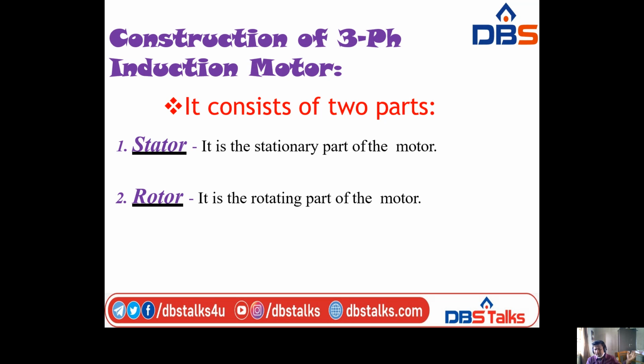As I said in the first slide, as we apply three-phase AC supply to the stator winding, it develops a rotating magnetic field, RMF, rotating at synchronous speed, right? That leads to generating rotational torque in the rotor, which moves the motor.